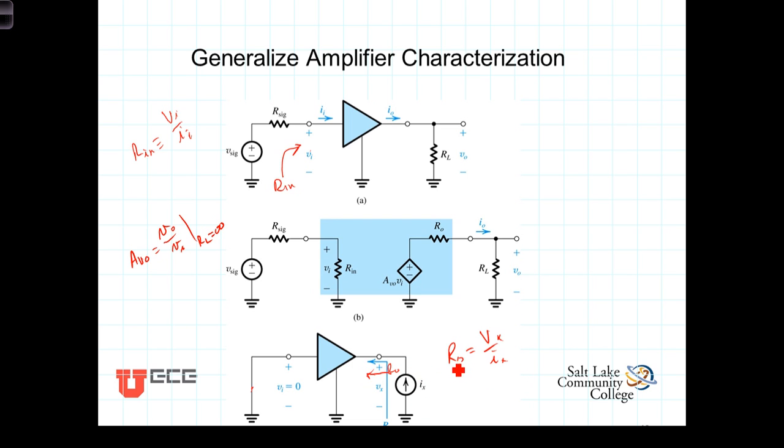And again, the Thevenin resistance, or the output resistance, is the ratio of the voltage to the current. So the output resistance is really just the Thevenin resistance that is experienced when a load is connected, and that internal resistance accounts for the voltage drop that occurs when a load resistor is connected.